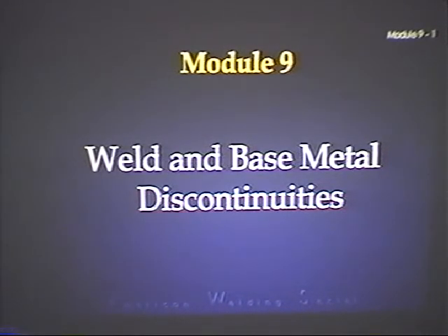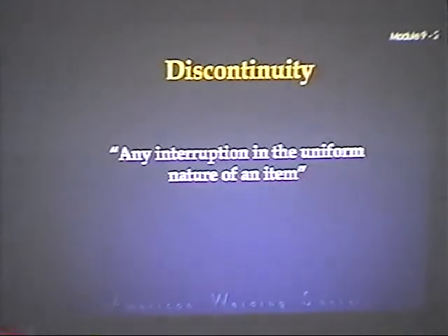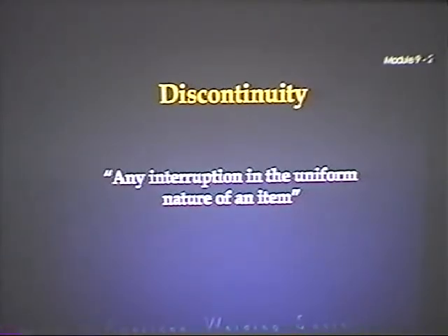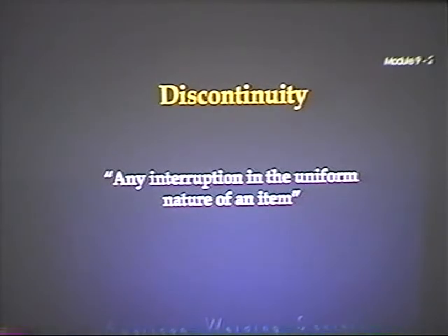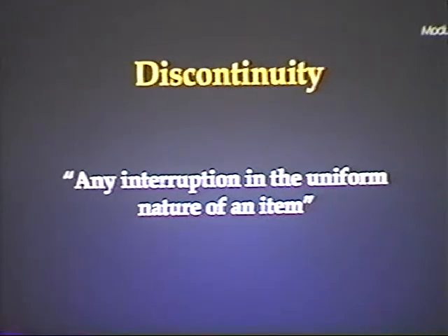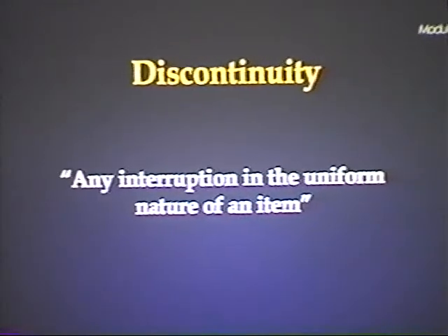Weld and base metal discontinuities. Well, what's a discontinuity? Any interruption in the uniform nature of an item. That's a discontinuity. When we're talking about welding, if you have slag in your weld, that's an interruption of that weld metal. Okay, so that becomes a discontinuity.